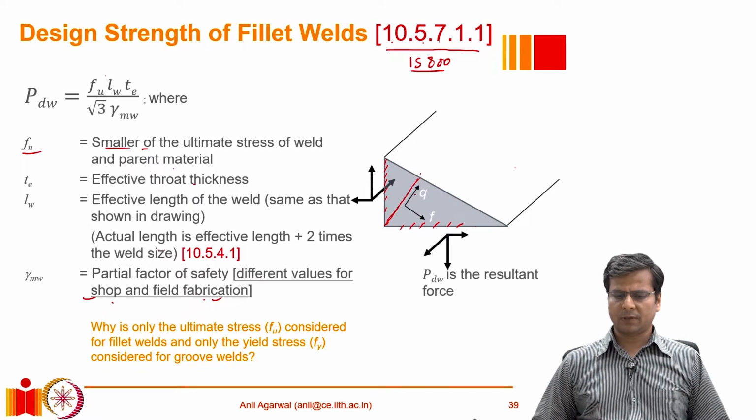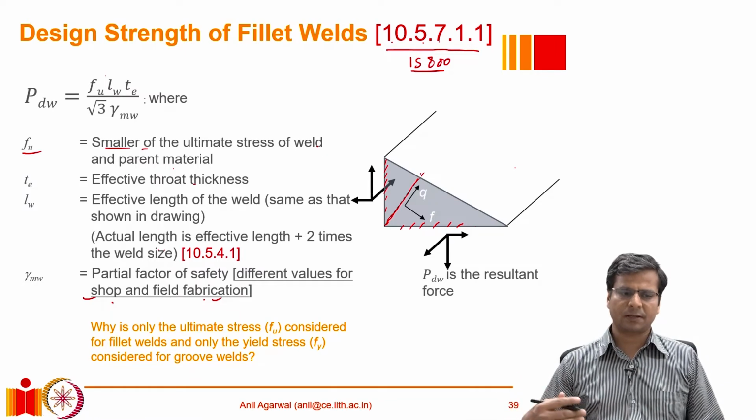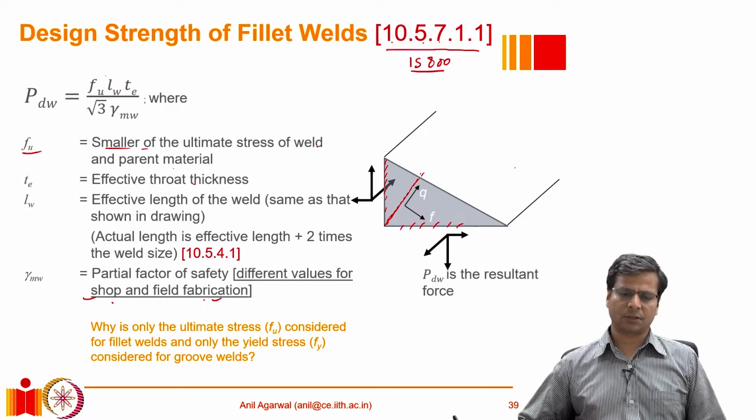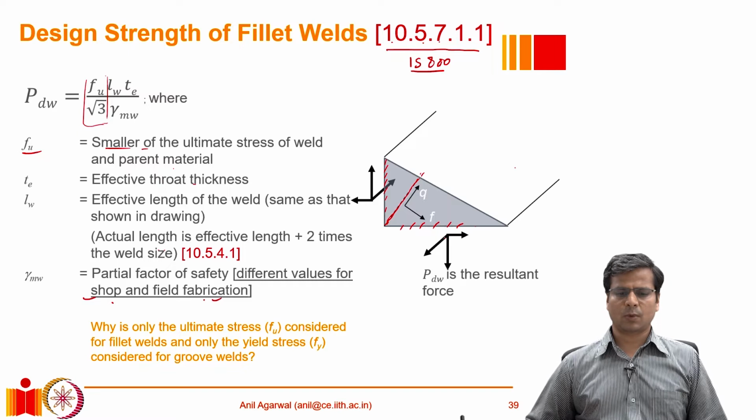That makes quite a bit of conservative sense, because a ductile material, as we know, has the lowest strength in pure shear. Whenever we have a ductile material, if we calculate using the von Mises criterion its strength under pure tension, or a combination of tension and shear, or pure shear, we will always have the lowest strength under pure shear. Therefore, what it is saying is that you take its strength under shear as its actual strength, no matter what the loading is.